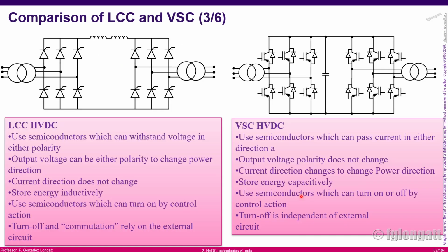Here, there is a comparison between LCC and voltage source converters, and there are many things over there, but one of the things that I want you to understand is LCC has been extremely useful for many years because they have the possibility of managing a lot of current and a lot of power. And that is the reason that they have been in the market for many years. However, they have issues about changing the polarity in order to change the power direction. That is one of the negative points.